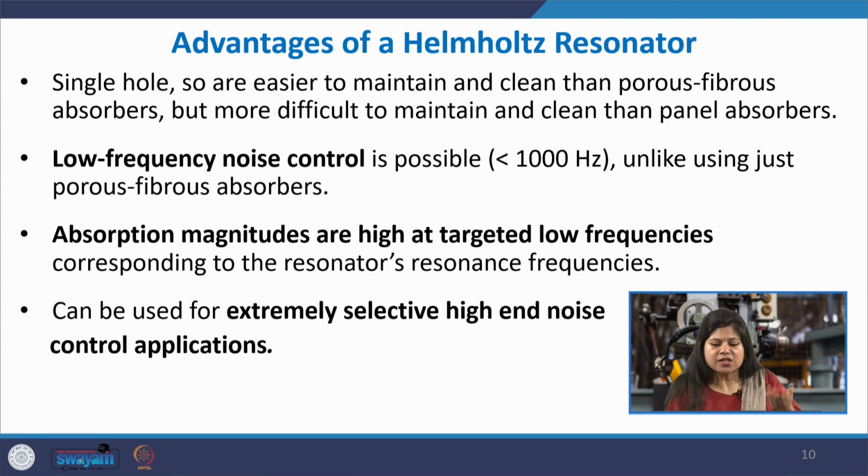But definitely they are more difficult to maintain and clean compared to the panel absorbers, because in the panel absorbers you just have a stiff panel, you do not have any neck which is a sensitive area with a small dimension or a micro hole or something. So, it is easier than porous fibrous, but more difficult than panel absorber in terms of maintenance and cleaning. Then low frequency noise control is definitely possible.